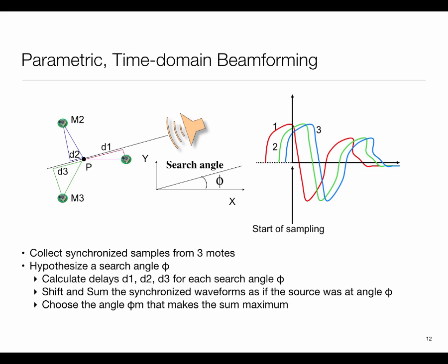This is an example of how this beamforming works. Roughly speaking, the idea is, let's say my acoustic source was out here. It will be sending out a waveform. That waveform will hit this sensor first, then it will hit this sensor, and then it will finally hit this sensor. And if these three were time synchronized,